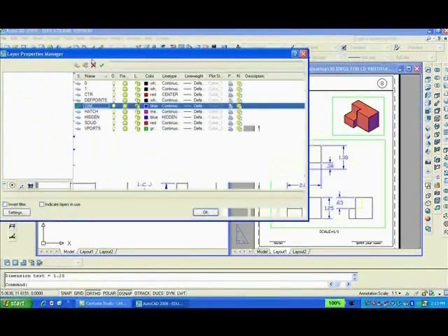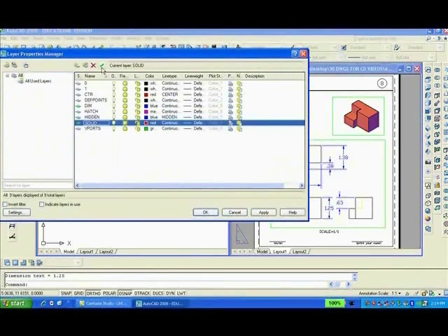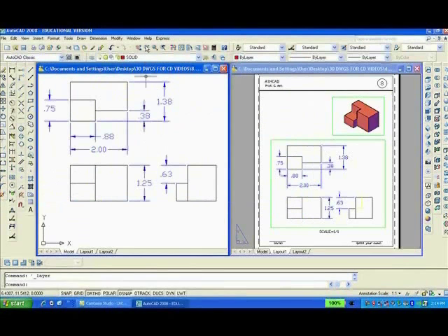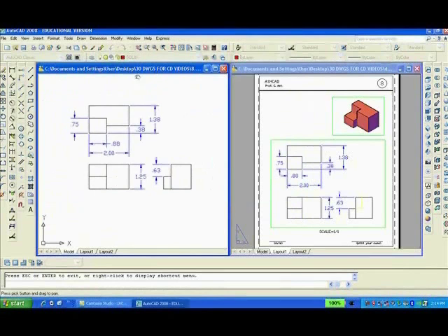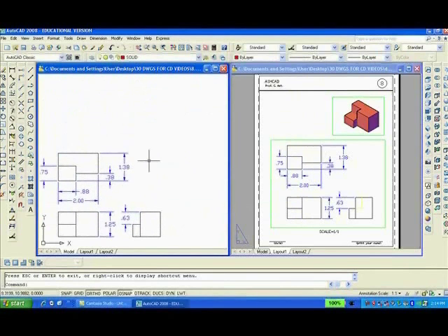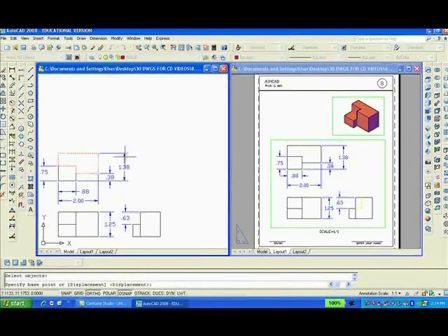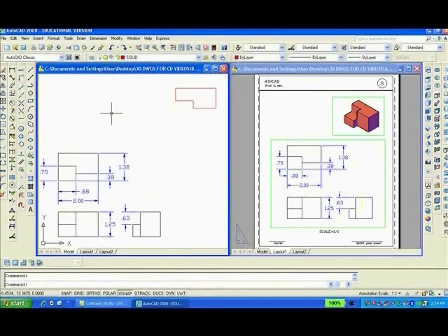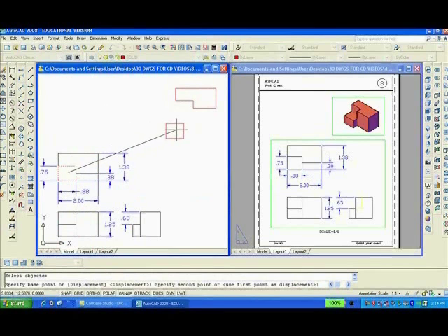Now we're going to make the solid model, so I'm going to switch here and make solid current for the layer. I'm going to zoom this down a bit and then pan over. So what I need here is a polyline. I'm going to copy that trace over the perimeter like this. C, enter to close. M, enter. L, enter. I want to move the last thing I drew. I'll take off ortho so I can move it to the upper right. Now I want to do the rectangle, two opposite points like that. M, enter. L, enter. Select that and move that up.